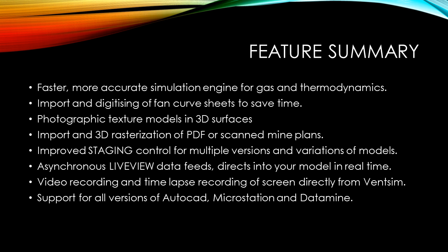One more question. Can you produce quick graphs on temperature, DPM, and velocity changes? The answer is yes, you can. And you could also do this in Ventsim3 to some extent. If you drop in what's called a monitor, which is one of the toolbar icons, into any of the airways in the mine, as the mine simulation progresses, either through a dynamic simulation or a live view simulation, it records the information flowing through that point in the mine in real time. Anytime you can click on that monitor, and it will do a full graph of any of the changes. So if the airflow or velocity have changed or the gases have changed, it'll draw a graph of those changes over the simulation period. And it can also export those graphs and data to Excel if you want to analyze them further.